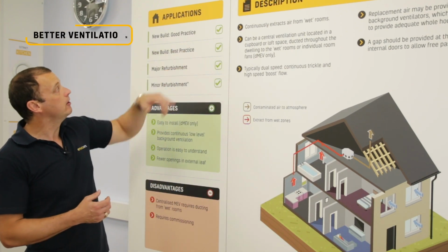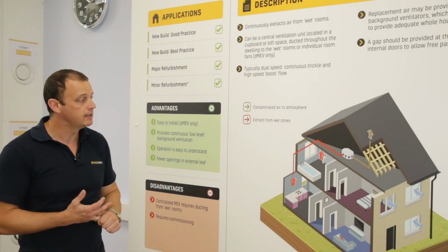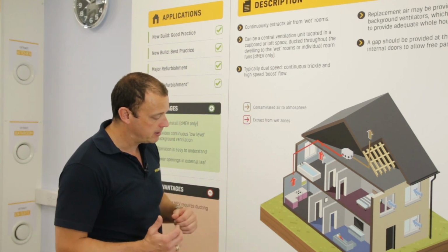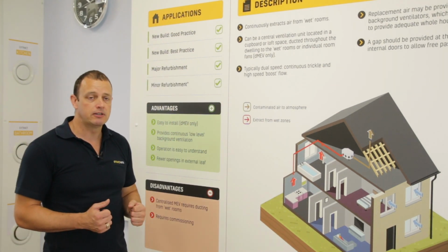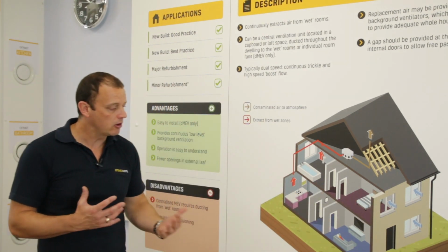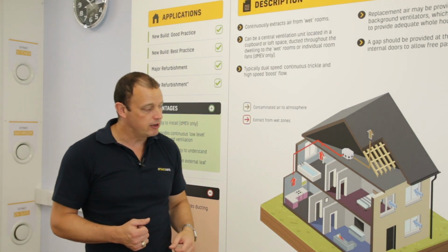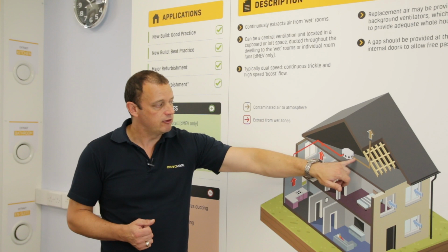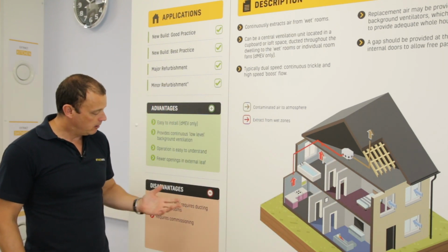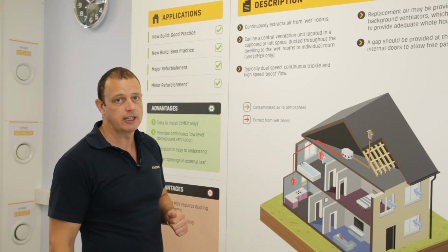Hence again why, for new builds, the Energy Saving Trust recognise it as best practice and good practice. It's an energy efficient way of ventilating a dwelling, a lot better than the traditional intermittent System 1 fans, especially when it comes to your background ventilation. You've not got all that air coming in, it's more controlled. So that's it for System 3 really. If you understand, obviously remembering that we've got centralised systems or you can have decentralised ones. We'll now finish off there and move on to the next system, which will be System 4, mechanical ventilation with heat recovery.